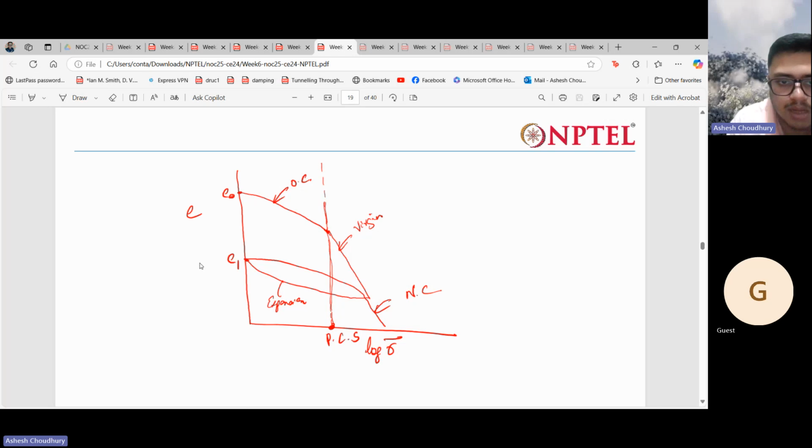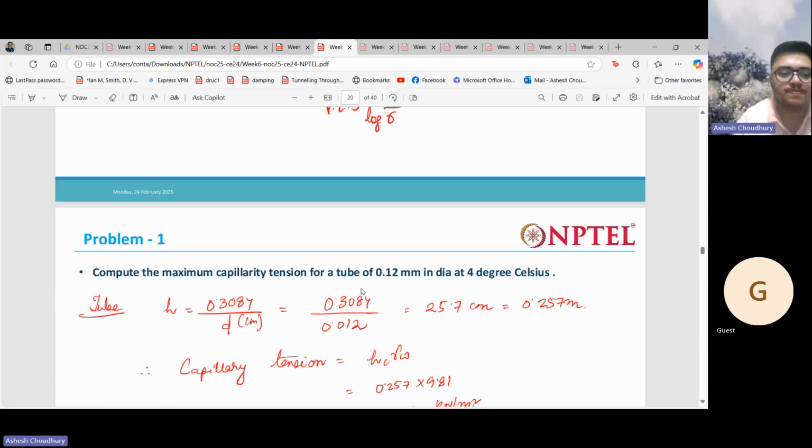So this is the basic idea. Say the soil was initially loaded to this part. So this is the pre-consolidation test. From here to here, it will have a curvature like this. Then as you cross the preconsolidation pressure you have a steeper line, that is because the soil is now encountering new higher stresses. Okay, then you reload it, it will leave it, and then unload it, then again reload it like this.